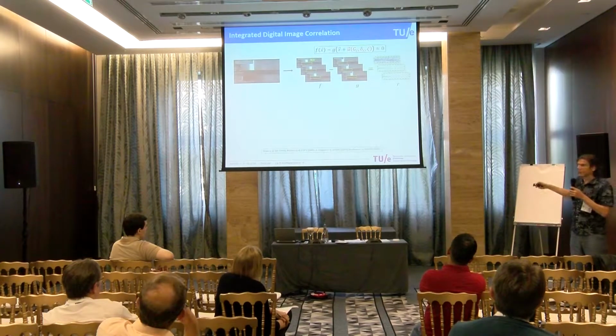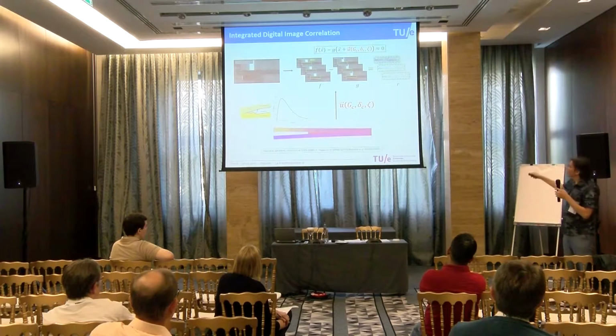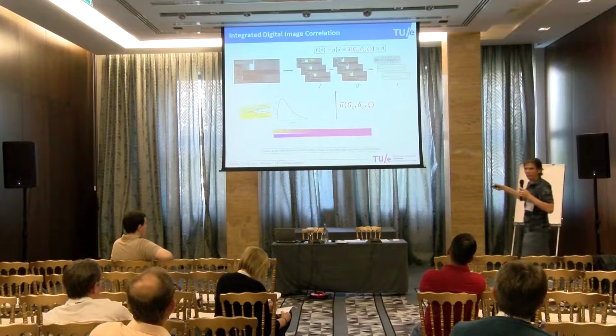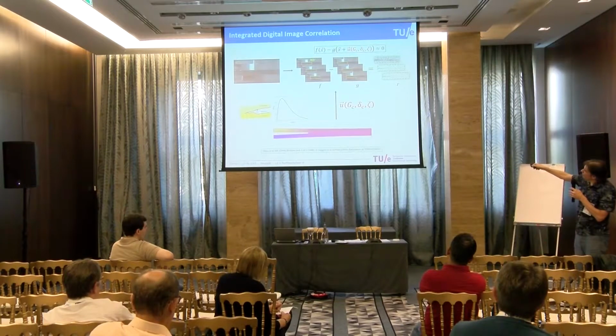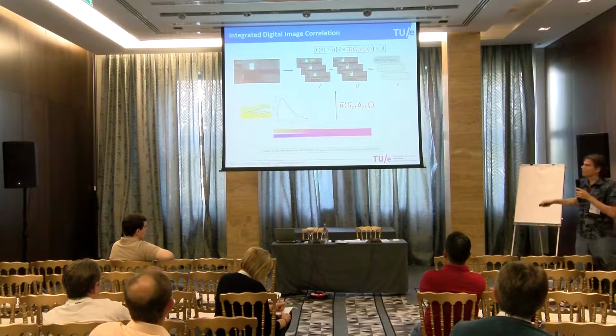The displacement field we get from a numerical simulation. This simulation depends on the material properties in these beams, but also on the cohesive zone model, which is what we want to identify. If we get this displacement field correct, then we can subtract these 2 images and get a 0 residual.